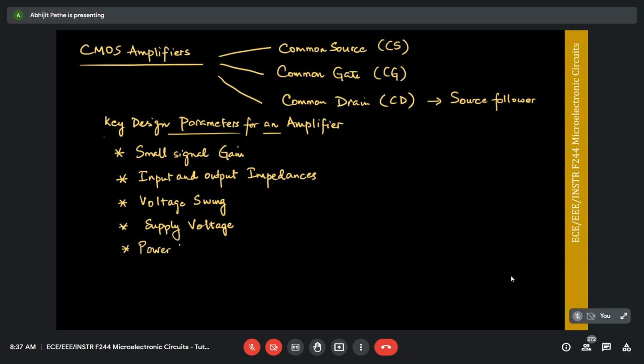Remember, which we looked at in some of the initial classes, you don't want this amplifier circuit to dissipate a lot of power. Which means that if you can avoid it, you won't want to use resistors in your circuit because resistors consume a lot of power. You want to figure out how you can do these designs without using resistors. Other thing which we spoke about is linearity, right? That is, I want to ensure that my gain is constant and independent of the input signal magnitude.